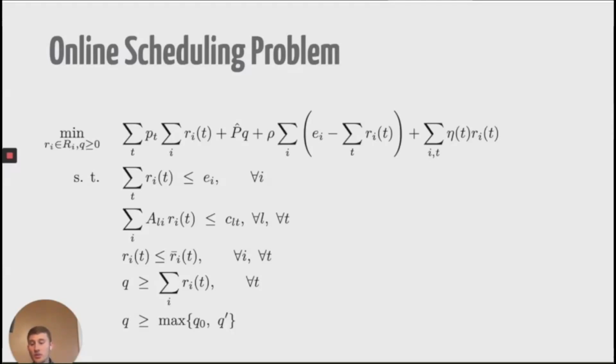The duration or the horizon for this optimization problem is roughly 12 hours. And if you compare that to the month-long optimization, we're only looking at a small slice. And so the objective looks very similar. We have an energy cost. We have a demand charge proxy. The reason this is a proxy is that we actually have to scale the demand charge so that we account for the fact that our time interval is much shorter. If you're interested in more of how we do that scaling, it's in the paper.